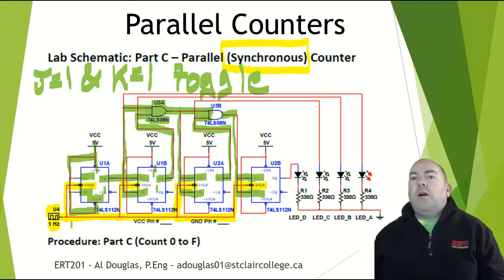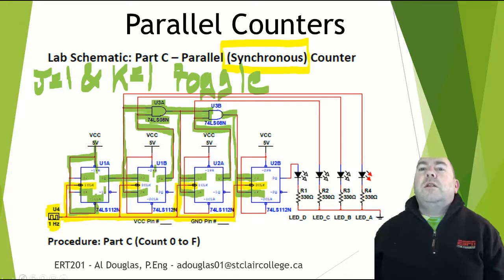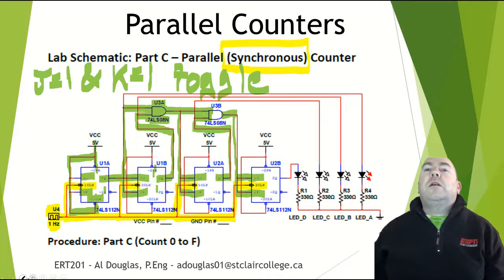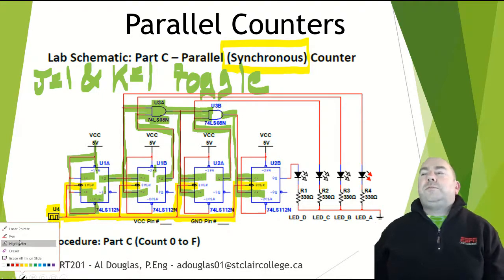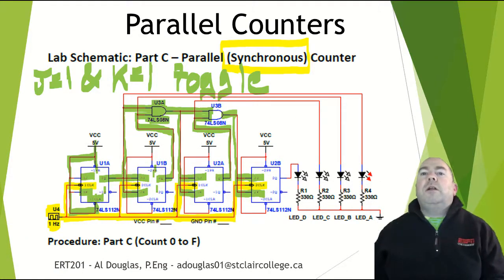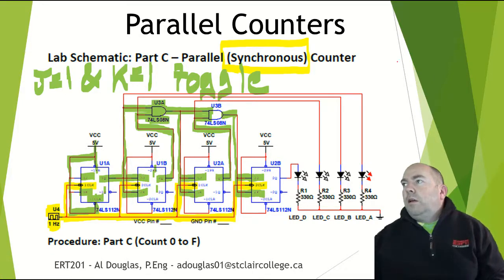So to look at that on a table, we are basically saying, my pen going here, let's think of this in red. Let's look at this as 4 bits. So we're going to clock these all. This is always just going to toggle. This first one here, this is always going to toggle back and forth every time we clock it.